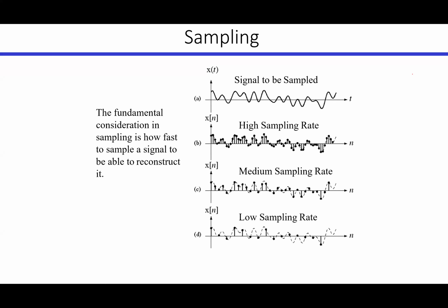Basically, if I am able to reconstruct my original signal after taking those samples and doing some processing on them, will I be able to restore the original signal? If that's a yes, this means my sampling is good enough. If I lose this information after the sampling process, then my sampling is inadequate and not good enough for me to reconstruct the original signal.